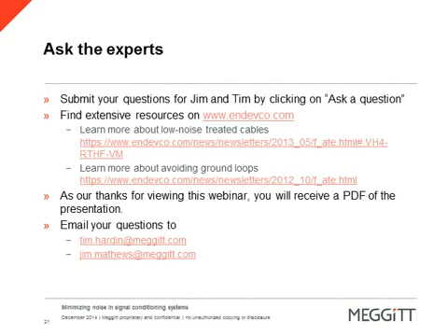If we have a piezoelectric transducer with the internal circuit isolated and cable shield isolated from case, will an overbraid used to extend the Faraday cage of the vehicle, connected to the case and the data acquisition system, induce noise from inductive coupling? No, I think as long as it's just tied back at the signal conditioner, the overbraid. This is like a double shielded coax, and it would be tied back to the signal conditioner, so you're okay.